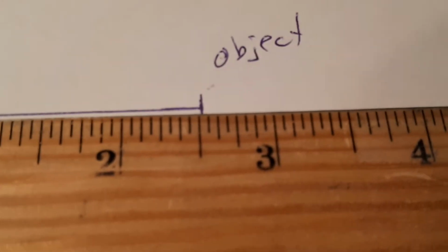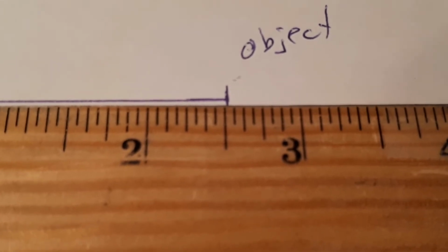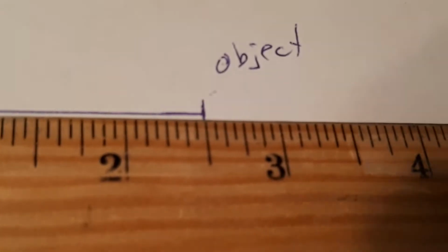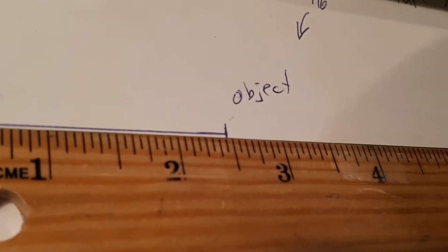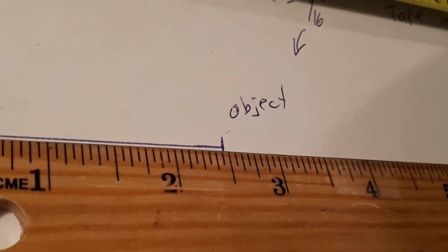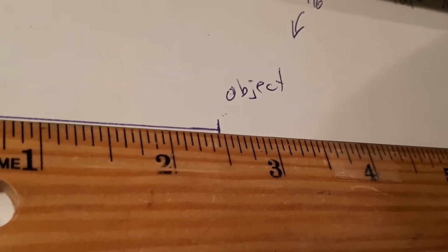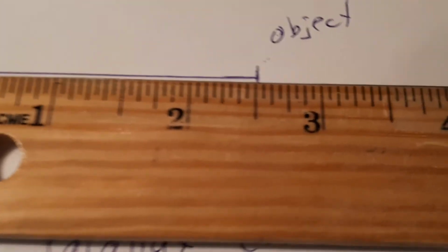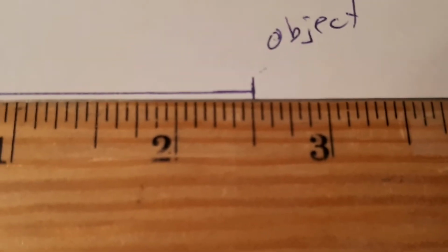Yet straight on, this is the proper way to do the measurement. It's just a little over 2.5 inches, or 2 and 4/16. And if I go to my left, you'll notice that the object now is moving to the left. I seem to have lost the focus again. We'll bring it back. If I go to the left, notice how the line on the paper is now moving, and it's less than 2.5 inches. That is known as parallax error. When making measurements, you need to look directly down.